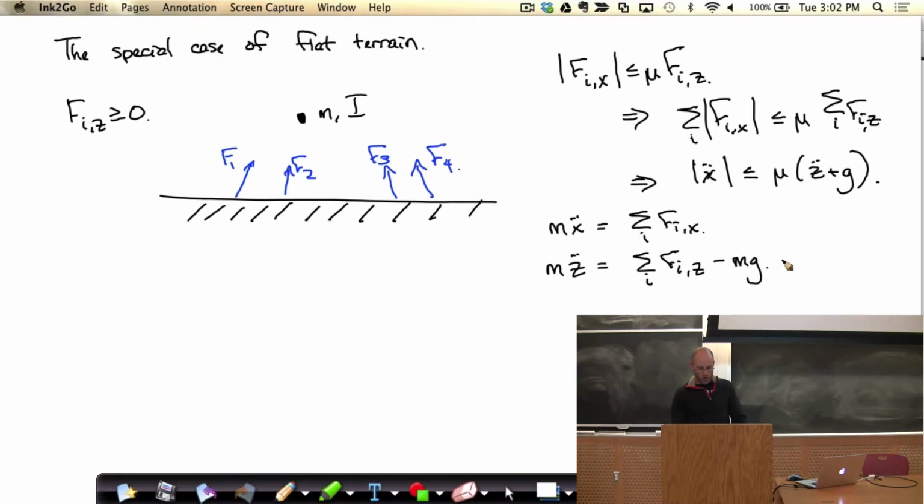Okay, so can you work that? Visually, that's like the bottom. So exactly, this is exactly right. Each of these individually has a friction cone associated with it. And what that implies is that I have somehow a cone on the accelerations of my center of mass. That's exactly the right point. So I can summarize the total constraints on these forces with a simple constraint on my center of mass acceleration, right? That might be a little conservative because of my inequalities here, but this is certainly a constraint on the total acceleration of my center of mass.